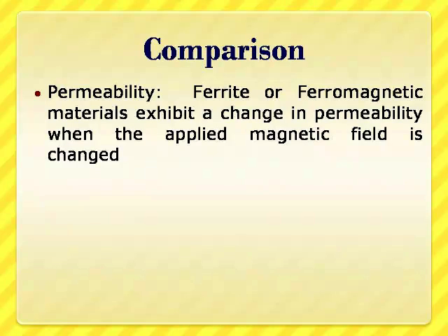The electromagnet will have the input as the current. So a computer controlled mechanism can be developed to change the current applied to this phase shifter, and hence the medium permeability is changed. The third one is also very successfully used in certain types of phase shifters called Reggia-Spencer phase shifters.